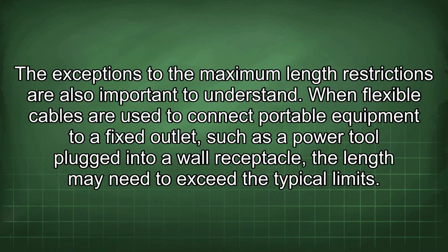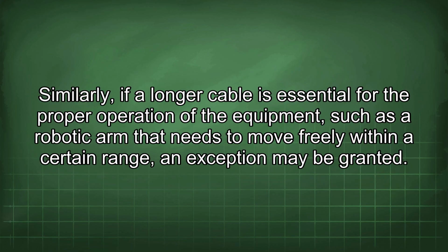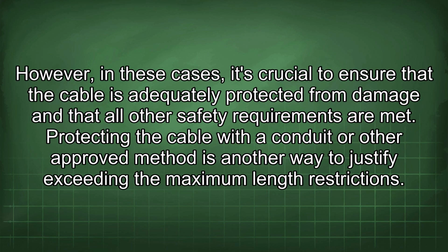The exceptions to the maximum length restrictions are also important to understand. When flexible cables are used to connect portable equipment to a fixed outlet, such as a power tool plugged into a wall receptacle, the length may need to exceed the typical limits. Similarly, if a longer cable is essential for the proper operation of the equipment, such as a robotic arm that needs to move freely within a certain range, an exception may be granted. However, in these cases, it's crucial to ensure that the cable is adequately protected from damage and that all other safety requirements are met.